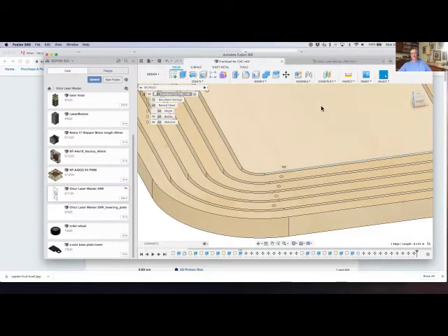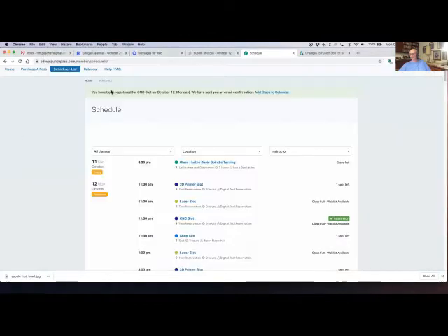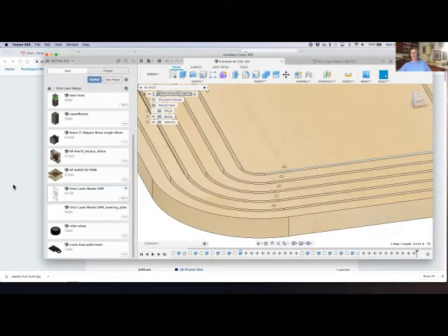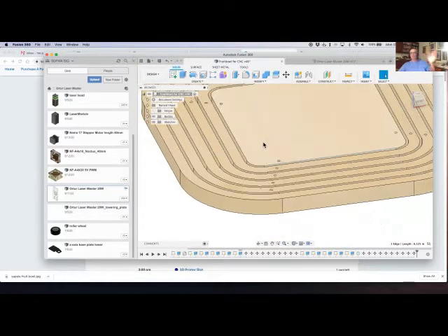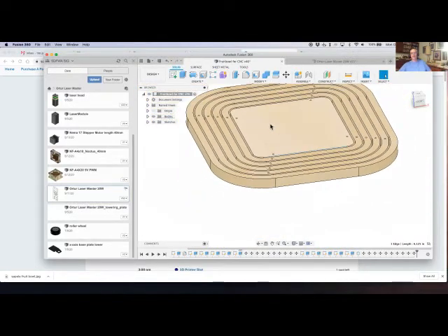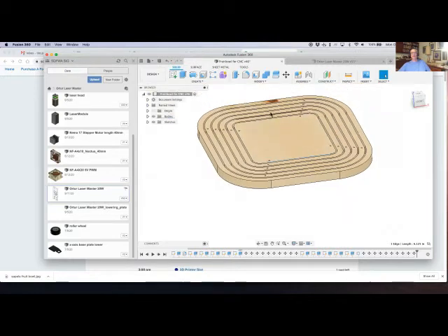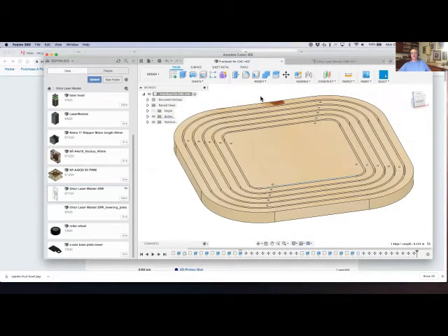I've had to fool it sometimes by saying, instead of a 125 slot width, I'd make it 4 thousandths larger. And then it's happy. But on the second cut, it would just fly through there really, really fast. But I've never figured out in Fusion 360 how to have a singular cut that was the same width as the tool.